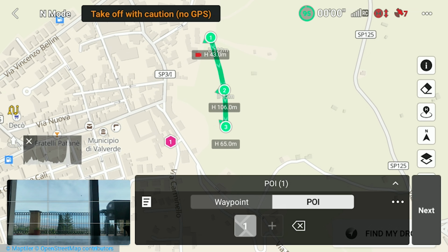For each of them, it is possible to specify the altitude, useful in case of a tall building, a mountain, or a tree. It is then possible to have all the waypoints or some of them facing a point of interest, in which case the altitude, camera orientation and gimbal tilt will be automatically entered, making the process of setting up the point easier. But on 99% of occasions, I suggest using the first method, setting the point on the field by flying and pressing C1 on the controller.